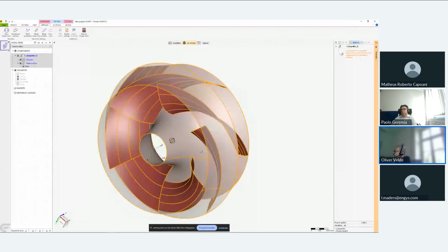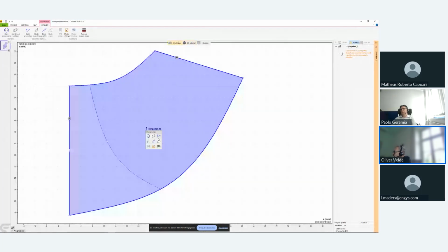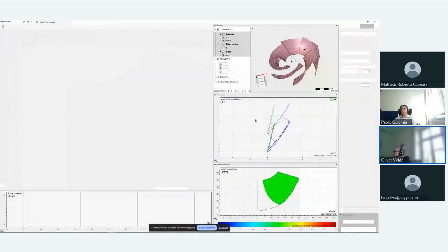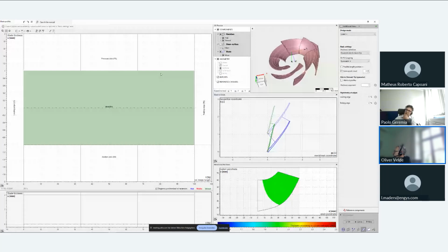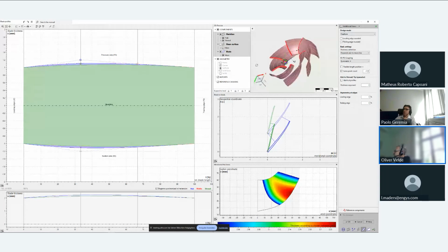If I press OK, then in 3D I now have blades with zero thickness. Thickness values can be added in the next design step, either in a linear way, like here, but also in a kind of profile way, where some control points, again Bezier point-based, can apply the thickness, and you see here how it's going to look in the 3D preview.